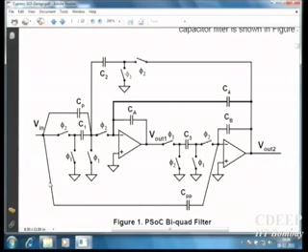Okay, so here there is a small point. When going from V out 1, so V out 1 is here, going from V out 1 to V out 2, instead of backward Euler, forward Euler has been used. The upper part still uses backward Euler, only this section uses forward Euler.